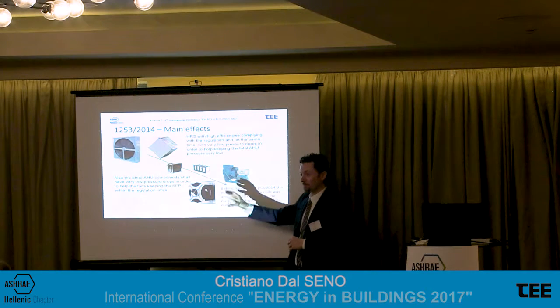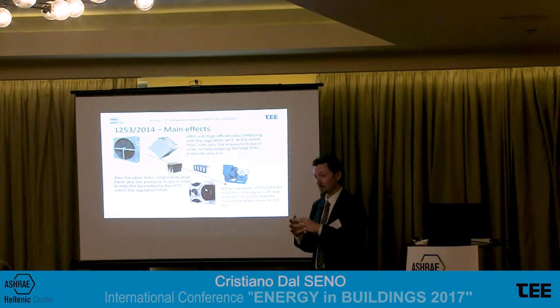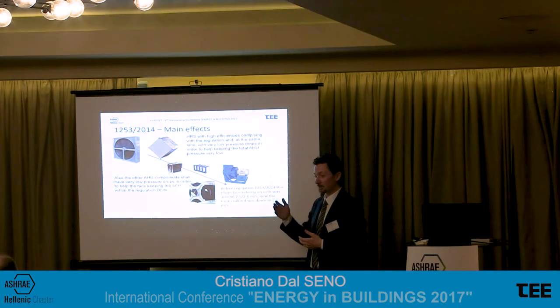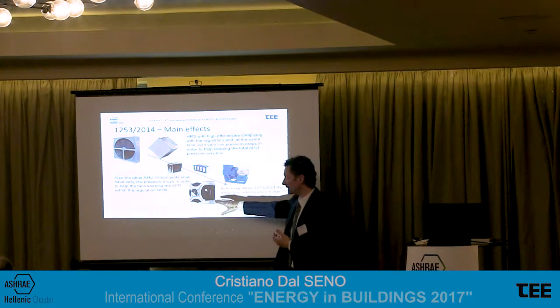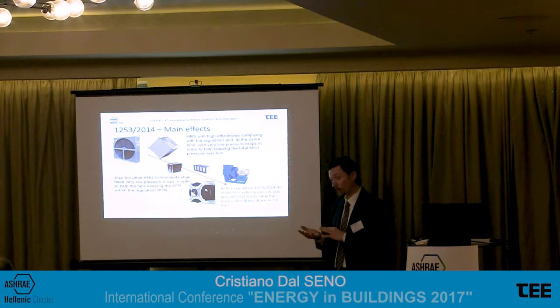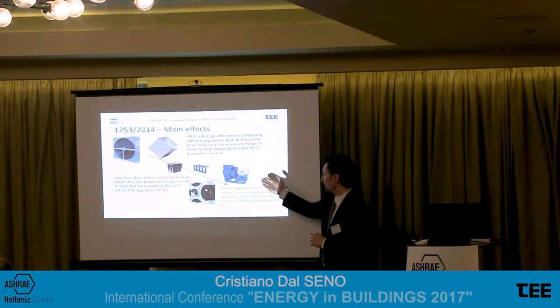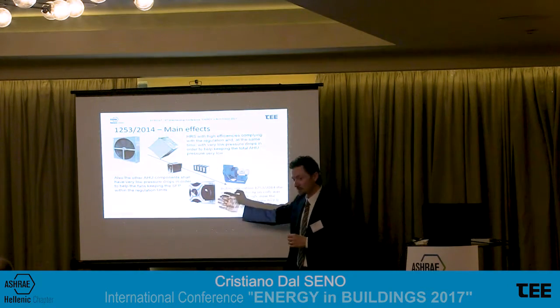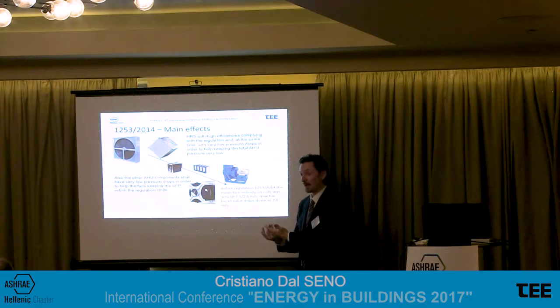And then fans. On the fans, we must look for better efficiency systems. We moved from IE2 efficiency to IE3. Now there are the EC fans, brushless motors that are considered in the market equivalent to IE4 efficiency systems. So if we move from typical belt-driven fans to plug fans or EC fans, this will again help in increasing the efficiency of the system.